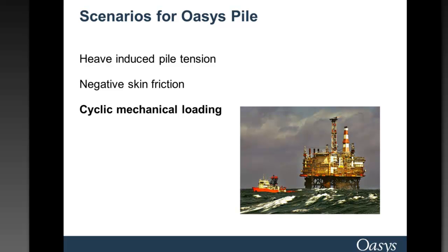The third scenario would be to consider cyclic mechanical loading, and this uses the staged loading feature that has been added. It could be from one extreme, perhaps offshore foundations where thousands or tens of thousands or millions of loading cycles might be experienced by the foundation, or it could be something smaller scale, like a simple pile load test where you have a number of loading stages or perhaps loading and unloading stages carried out during a pile load test.